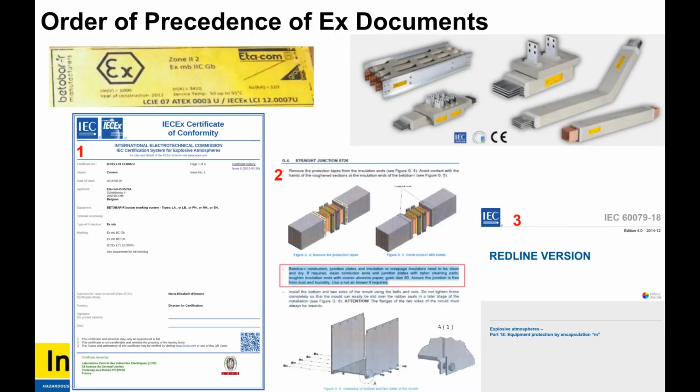Now the ones where you have the bus duct, the reason it's used is it's much better than cables. It can withstand fires for longer. You can put more current through in a small space because it has thicker, stronger insulation, higher dielectric strength than a cable does. So the weight would be less than cables, the size is less than cables. Over the long run, the initial cost may be the same or more, but the benefits are immense.